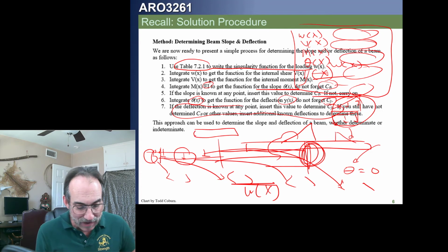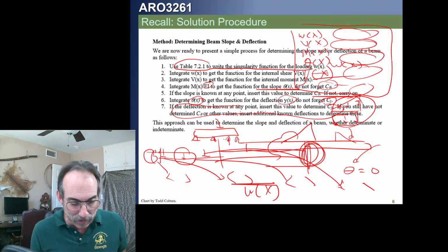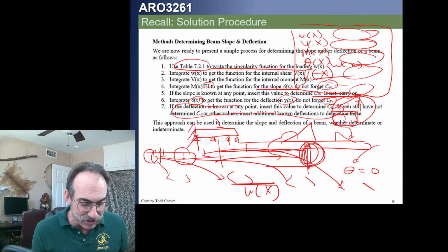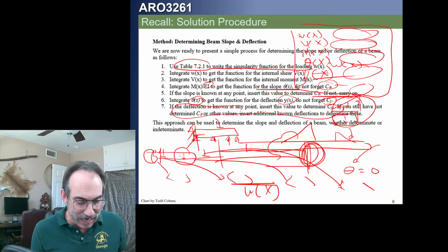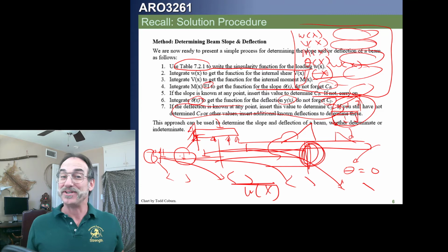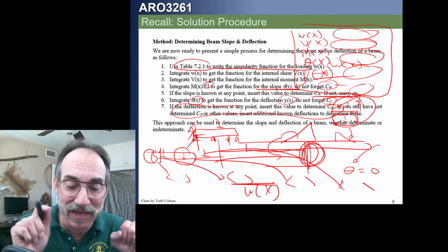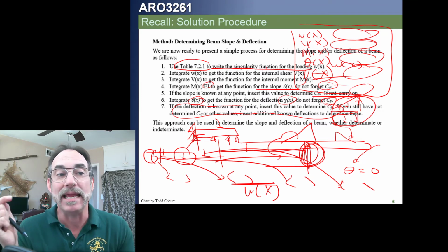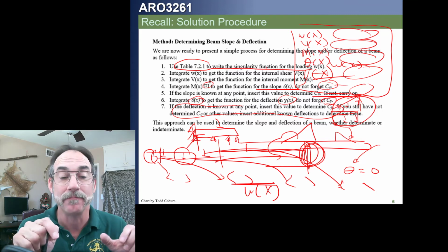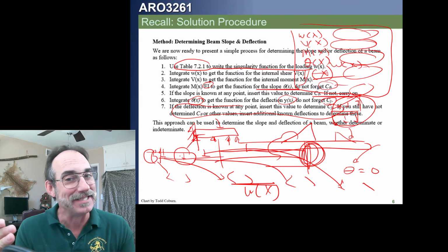For example, if we have a beam that has two supports, that's going to be a determinate beam. If there's a third support, that's now indeterminate, but we can impose a deflection constraint there. If there's another constraint, that's another indeterminacy, but we can impose a constraint there. If we actually end up being fixed on the left end, that's even more constrained, but now we have a deflection and a slope constraint. So indeterminate beams are the exact same thing as determinate beams, except that we will just do more plugging and chugging when we implement the other constraints that made it indeterminate. It's as simple as that.